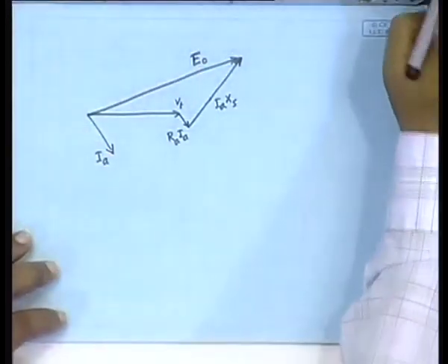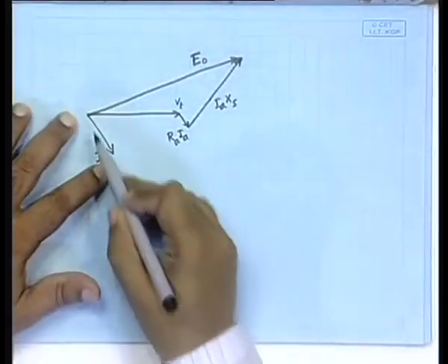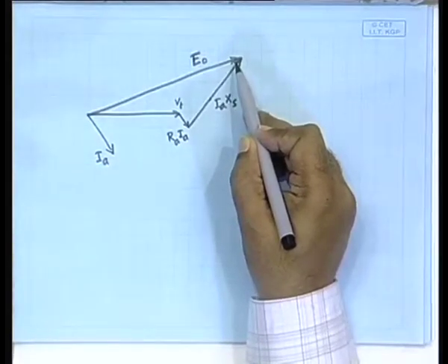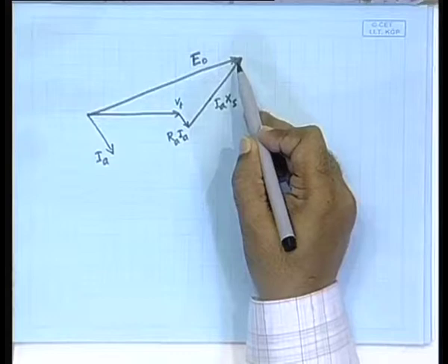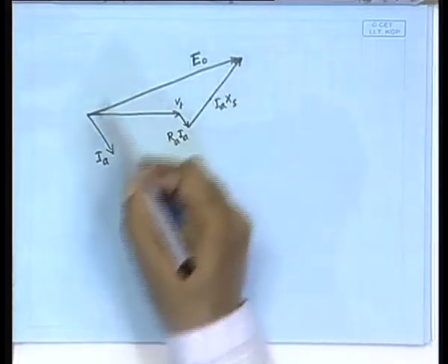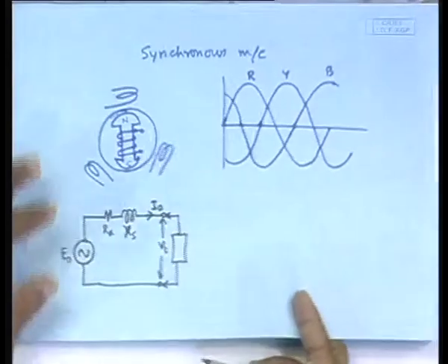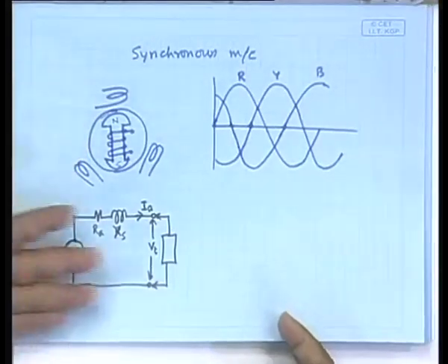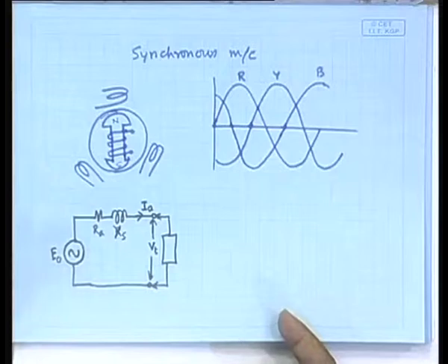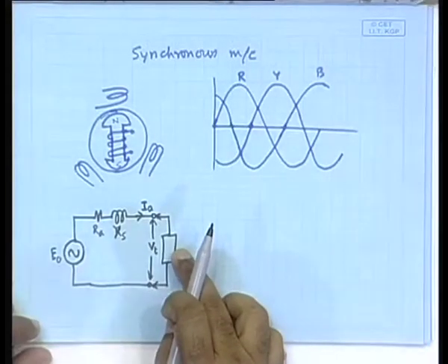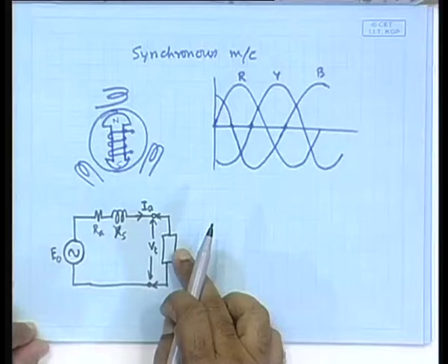So, depending on the character of the load, you can always generate the required amount of generated voltage. So, you can easily see that by this mechanism the synchronous machine is able to supply reactive volt ampere. You do not need a capacitor here, right. The machine itself is generating the reactive power that is being consumed by this fellow. Clear?